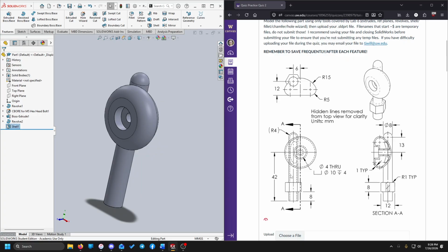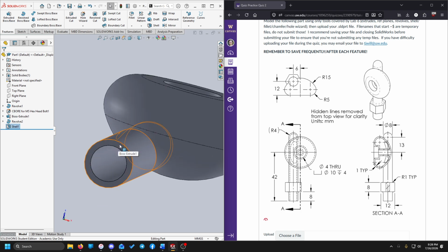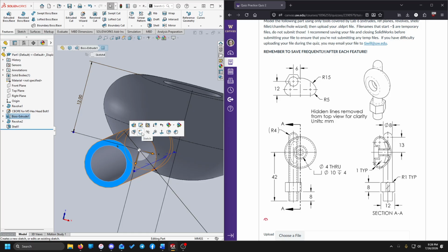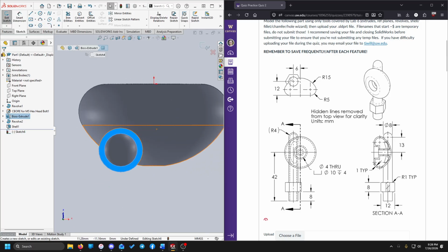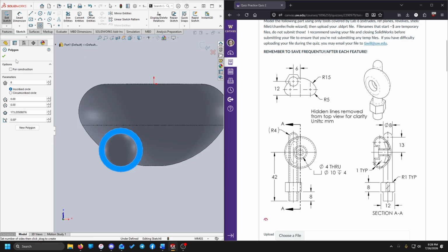All right, last bit, we've got this collar and then the fillets, and then we are good. So for the collar, we start on the bottom surface here, create ourselves a sketch on that face. This one is going to end up as a hexagon, so we'll use our polygon tool, 6 sides, and we want it to be centered in the middle of this circle. So if we sort of bring the cursor close to it, that looks about right. Then we can draw that out.